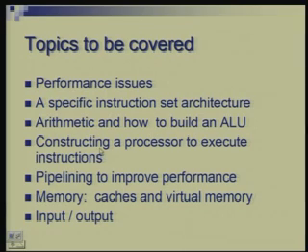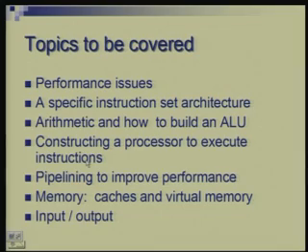So, ALU is just one part of the processor. You have to put in register files, you have to put in buses, you have to put in a program counter, and you have to put in a controller to make the data flow into various components properly. So, next we will be dealing with the design, the flow of data, the data path, and the controller.